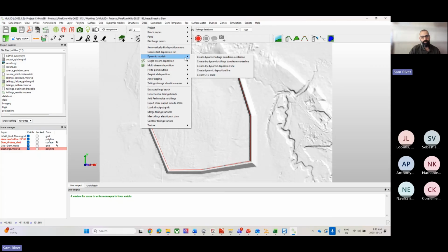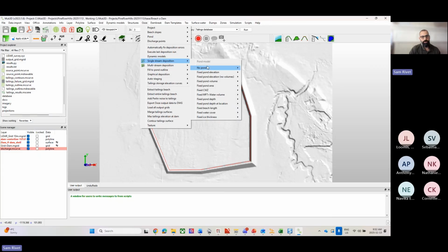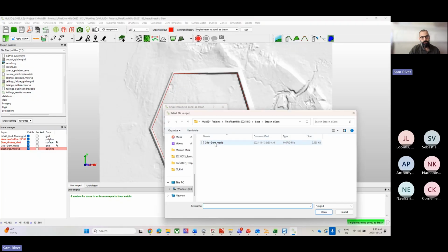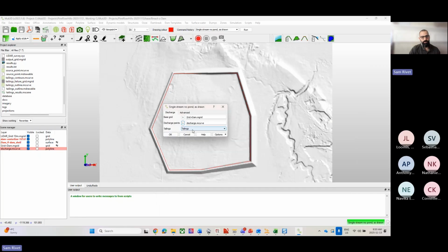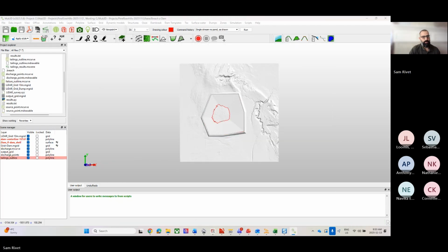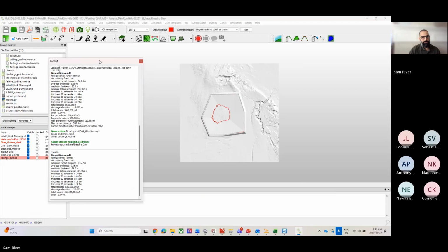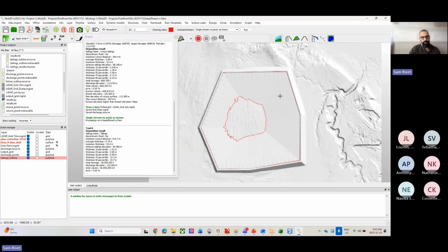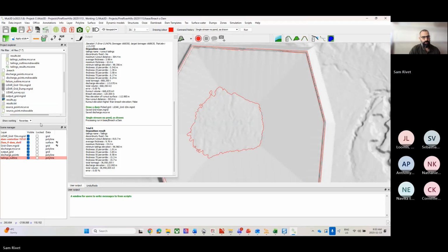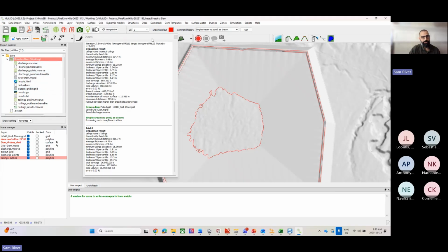All right. I was just checking the chat quick. Single stream, no pond. We'll go as drawn. Pick this grid with the dam merged in. Choose those discharge points. We only have one tailings type. We've selected it. Hit OK. So we can see here we've created our output grid now. We have tailings. That's going to be saved automatically to our working directory, so I don't have to worry about saving that.